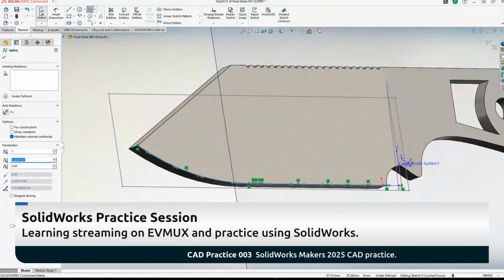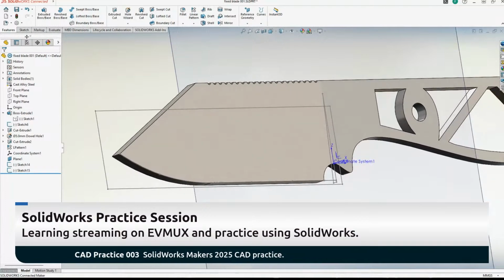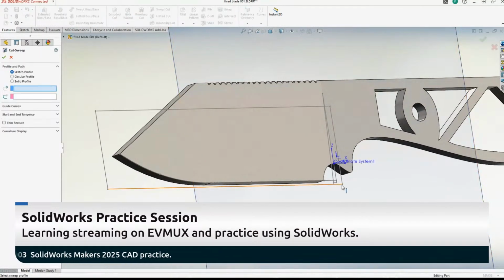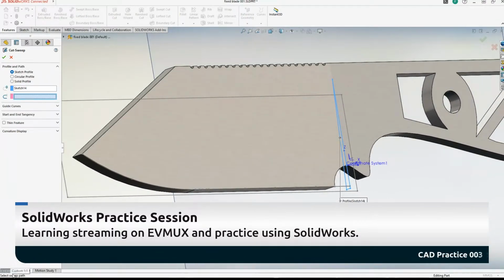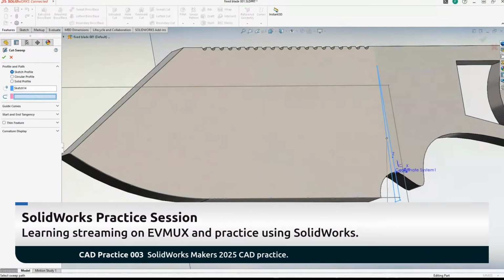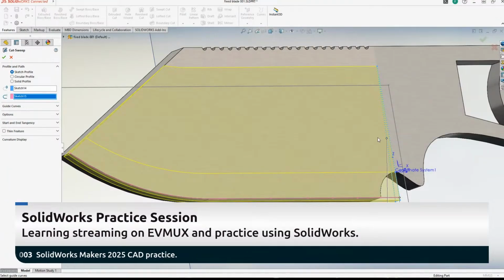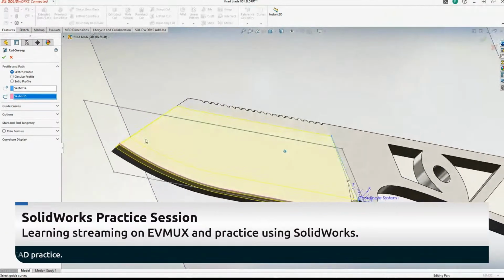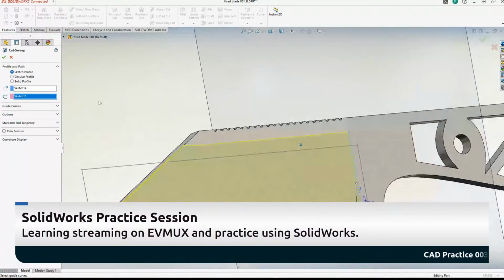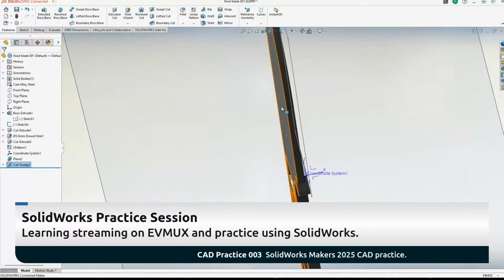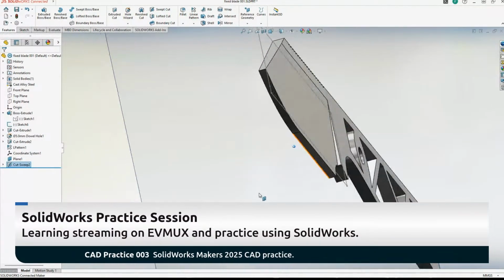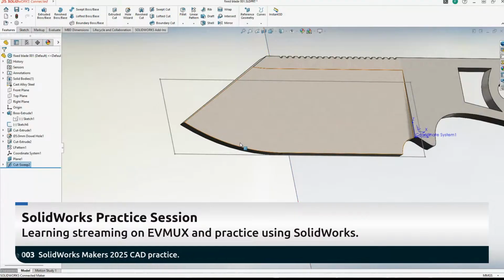So now we can exit this sketch and rerun that same swept cut. Now, did you pick the one line? Okay, it didn't pick the guide curve. So you can see down at the bottom, it always tells you what you need to do next. Down here, it says select sweep path, and that'll be this line. So as long as they're touching together, and the tool knows what to do, just hit the go button, and there we have a uniform line that follows the contour of this.